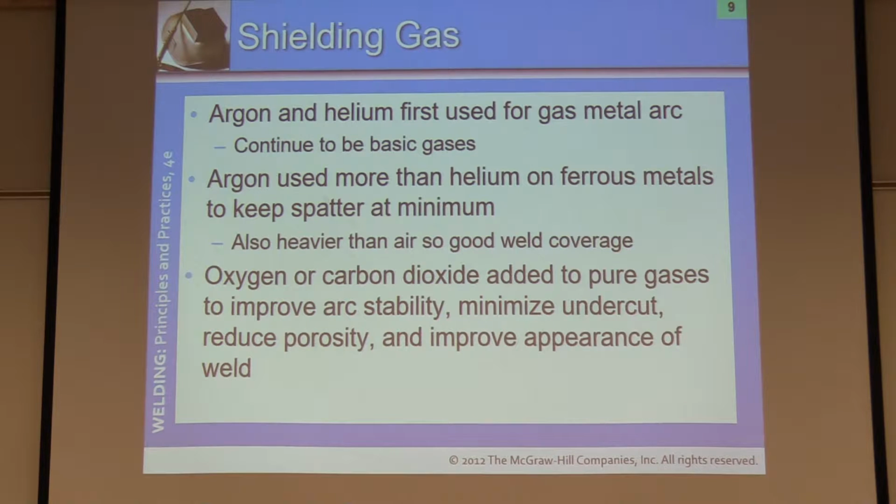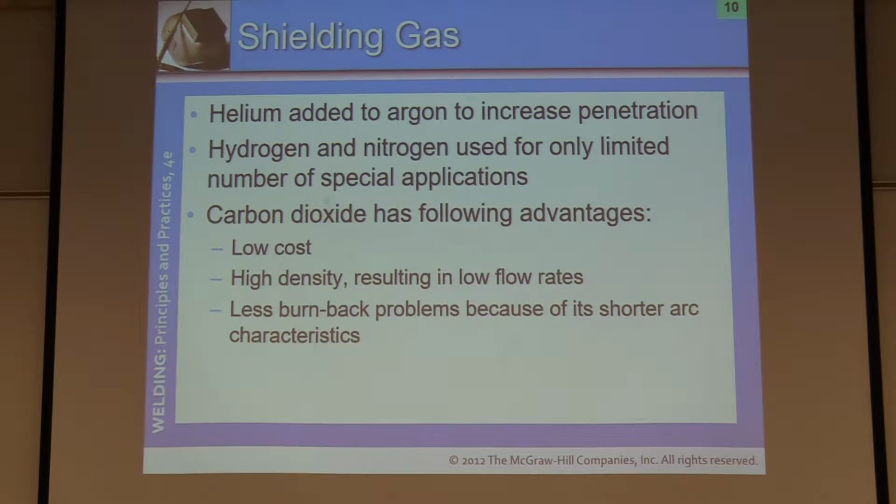Argon's used more than helium on ferrous metals to keep spatter at a minimum. It's also heavier than air, so it gives better weld coverage, especially in a bit of a cross draft situation as well. Okay.